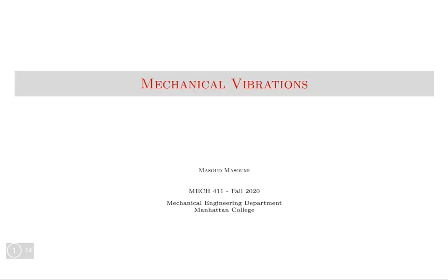Now, what I'm going to do today is talk about a different type, a type that is more familiar to you, and there is a reason we did not start with this, because you will see this is less straightforward in the way we deal with it. Viscous damping is the most common one that we use when we deal with systems, because it's very well behaved. When we are writing the equation of motion and we want to solve it, when we use viscous damping, it's much easier to solve the equation and find the system response.